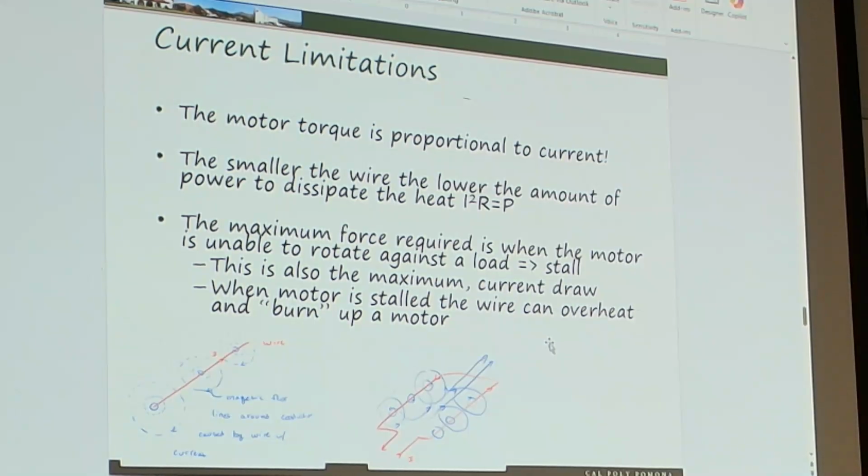We have so much torque, but my motor can't deliver that. And I'm giving it current, I'm giving it the power it's going to take. It says, to get the current and the power, the I squared R, the VI, I need to get that motor to produce that amount of torque, or that amount of power for the torque, which would be the power. Rotational power is torque times velocity, or omega.